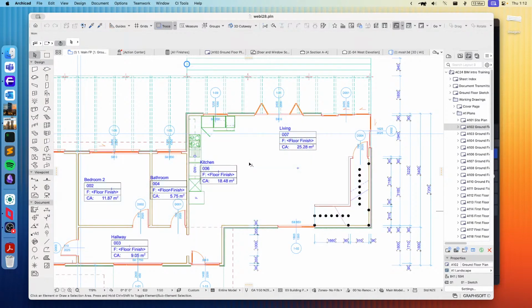And they also have accompanying wall plates in 3D, so that means that in your elevation views and 3D views, you will also be able to see a representation of the electrical symbols that you're placing. So you don't have to place a symbol somewhere in 2D and then also find a matching 3D symbol. Everything displays in both 2D and 3D using symbolic views and wall plates for 3D. So they just stay together. You don't have to worry about placing multiple different pieces.